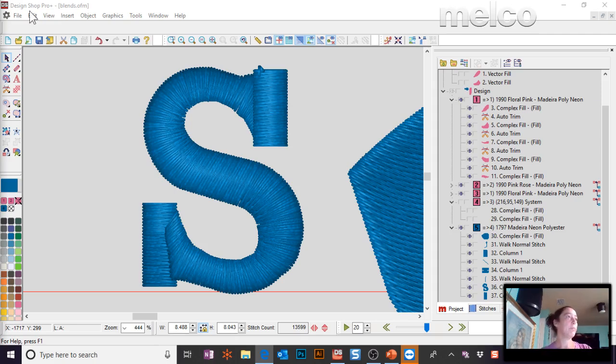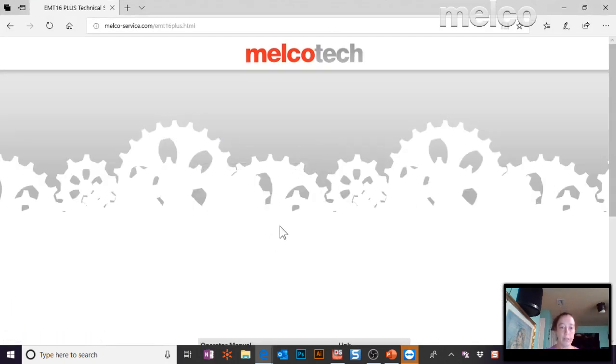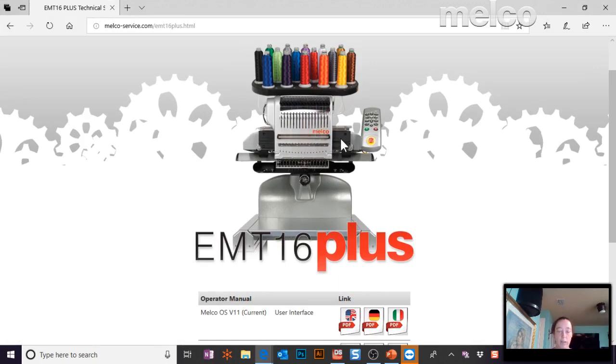All right. So I'm going to bring this over here. All right, so on the front of the machine, you've got these black covers, right? So you've got a cover here and a cover here. When you're doing your maintenance, some of the steps, this is in the 30,000 stitch maintenance, the one that's intended to be done quarterly, this needle case will move off to one side. You'll pull out 4 screws plus the little screw down here, and you'll take this black cover off.